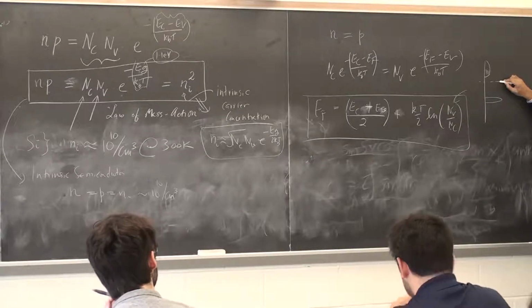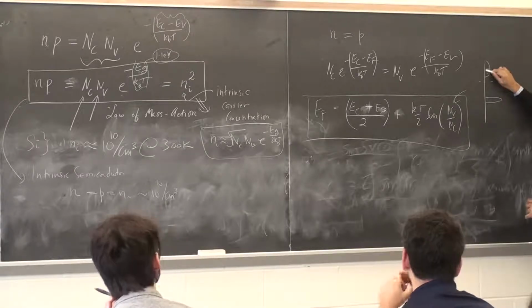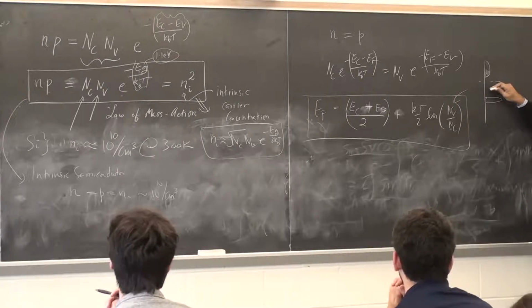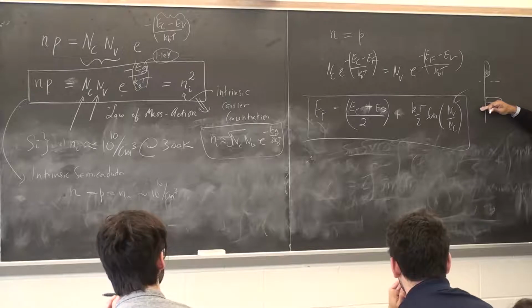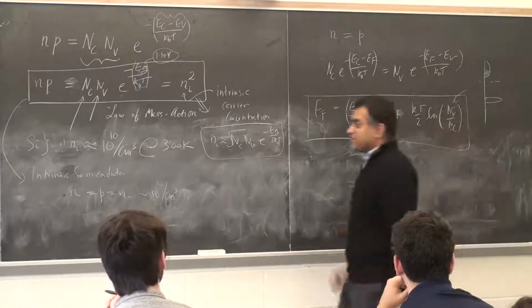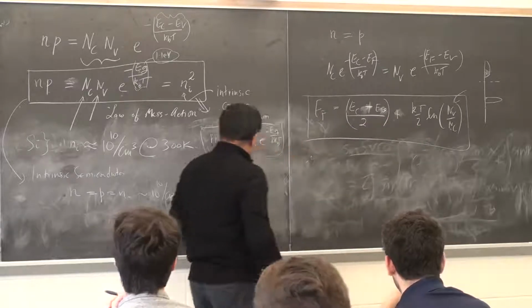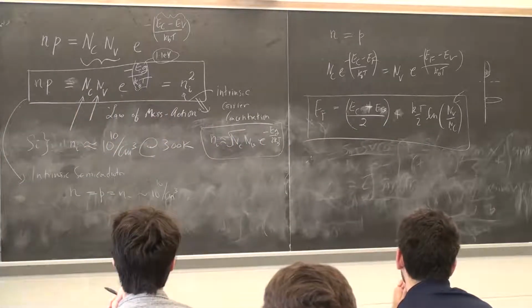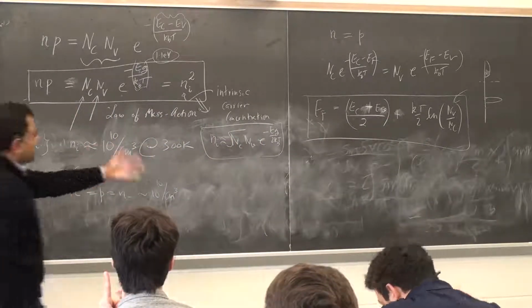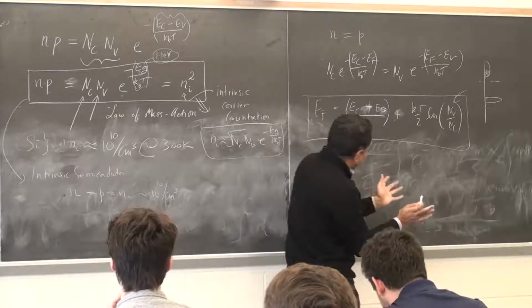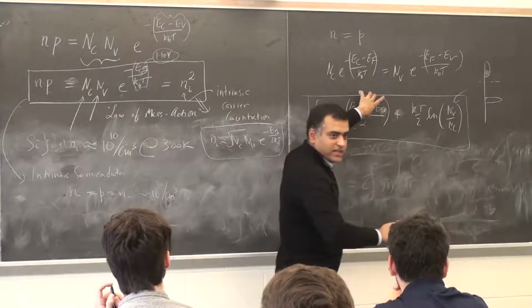Does that make sense? Because then it has to populate equal numbers of electrons and holes. It has to be farther away from the higher DOS state, so that it balances out. And you can evaluate all the numbers here, and you can see at least if NV and NC are exactly equal, it should be right in the middle, right?